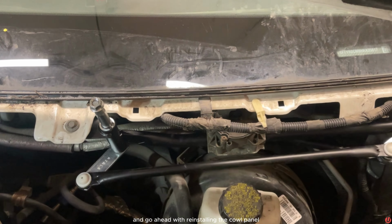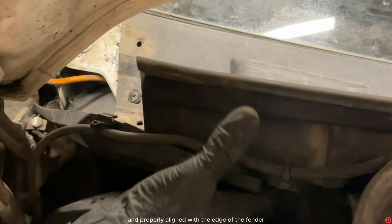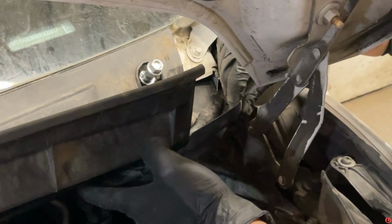Then, we will reinstall the 3 push pins to secure the cowl panel to the cowl dash panel. We must make sure that the driver's side and passenger side fender trims are placed in position and properly aligned with the edge of the fender. Then, we will reinstall the 4 push pins to secure the 2 fender trims on cowl panel and the cowl dash panel.